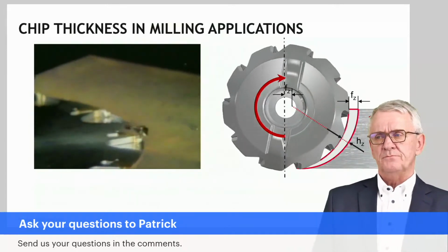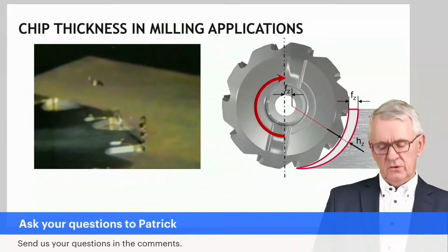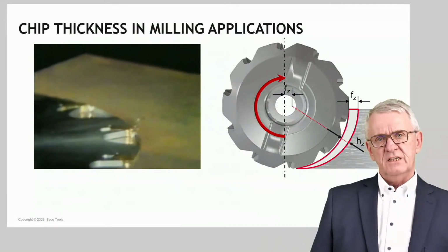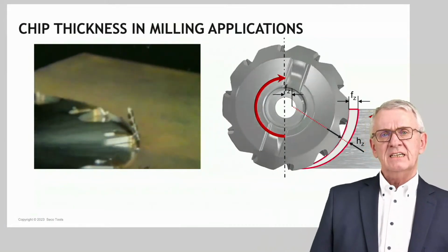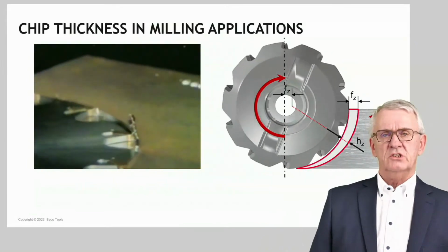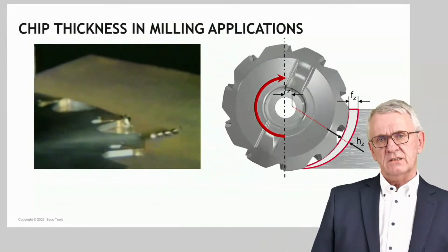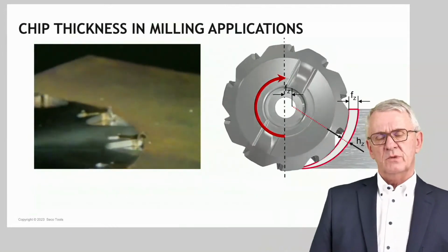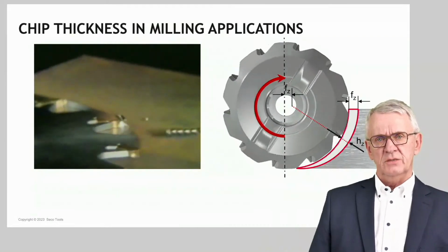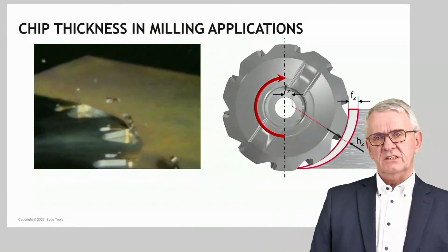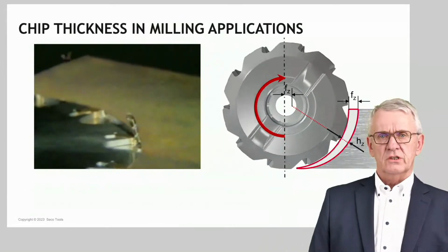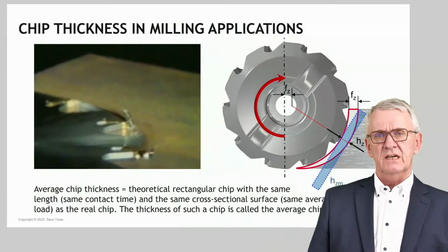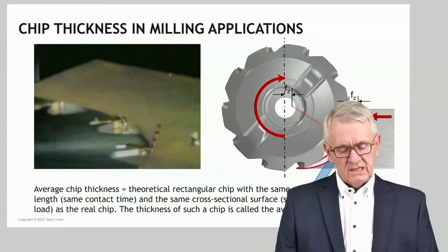And to make that happen, we said, okay, we are confronted with a situation. A milling cutter is working with a certain feed. Take here feed per tooth per rotation, Fz. That leads to a cutting edge cutting a chip with a cross-sectional thickness, which you see here, which is the gray zone limited by the red lines. That's the section of a chip. And the thickness of that chip is changing constantly from a certain maximum value to a certain minimum value, in the example as given here, which is down milling. Well, we kind of